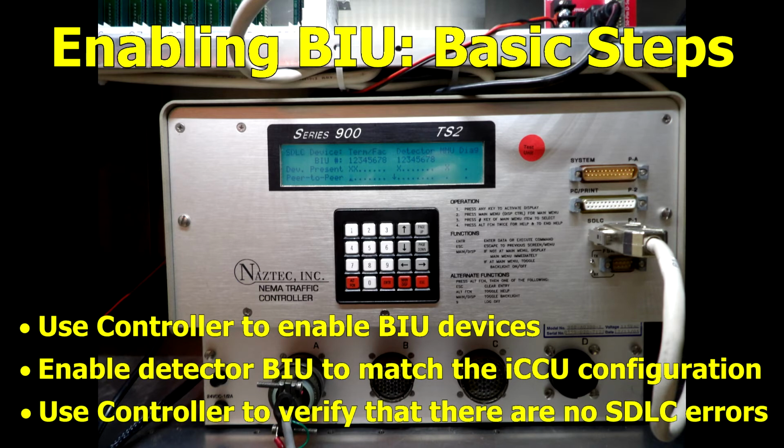Use the traffic controller to verify that there are no SDLC errors on the BIU device that was enabled. If there are errors on the newly enabled device, make sure the iCCU is powered on, the SDLC cable is connected, and the BIU number matches the iCCU configuration.